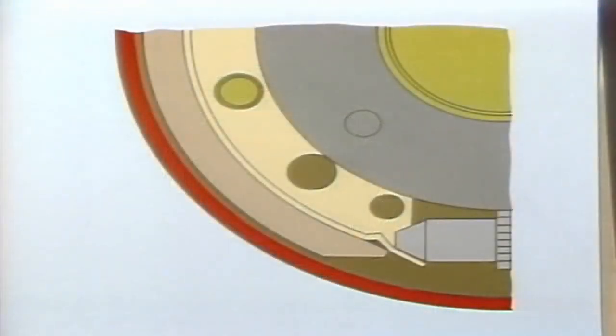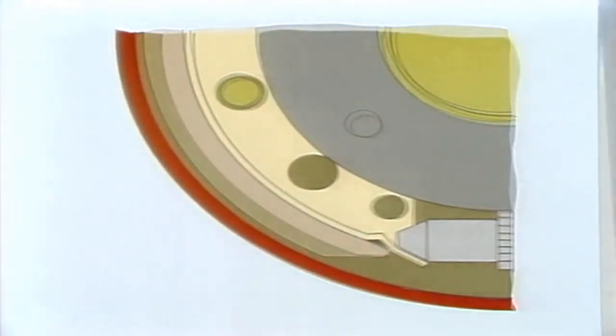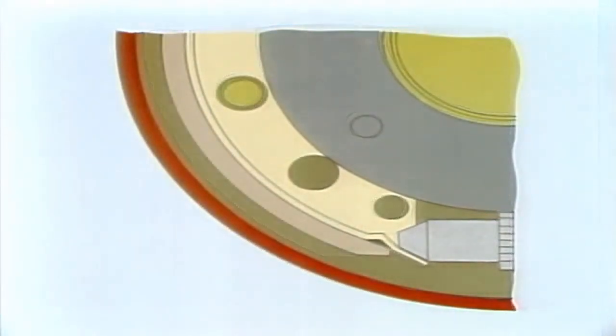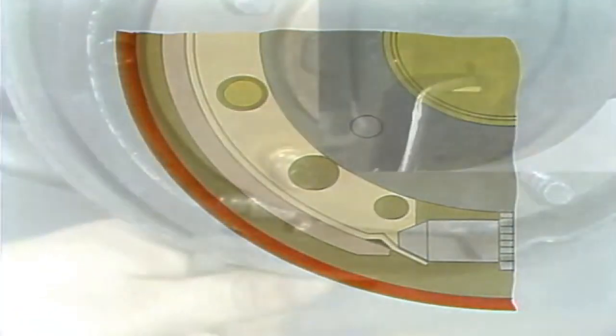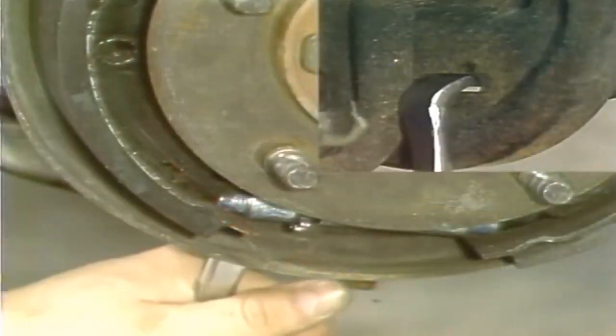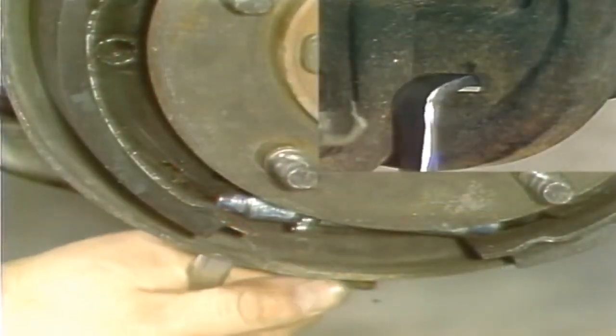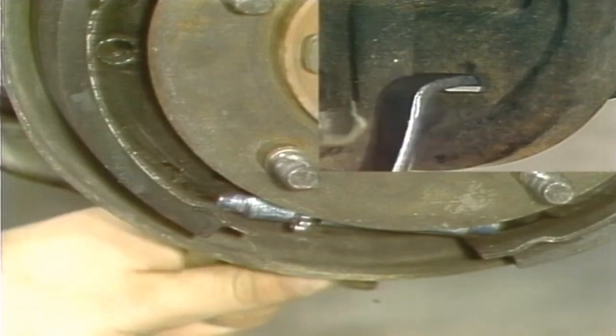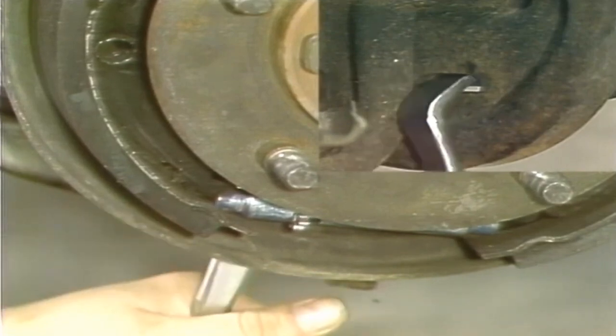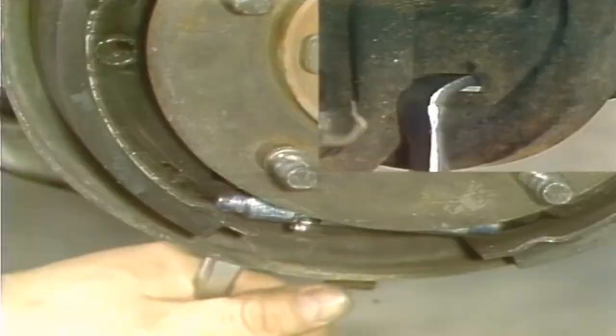One more thing you need to know about drum brake operation. You remember we said brake linings will wear with use. The brake pedal then has to travel farther to force the brake lining to make contact with the drum. To close this gap to normal, you'll be using an adjustment tool to rotate the star wheel on the adjustment screw. This will return brake pedal travel to normal. Excessively worn brake linings will of course have to be replaced so the shoe doesn't score the drum surface.